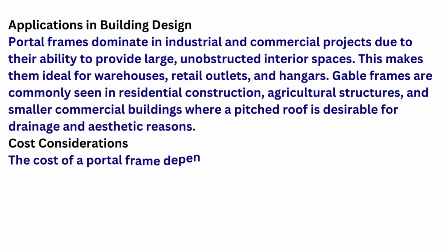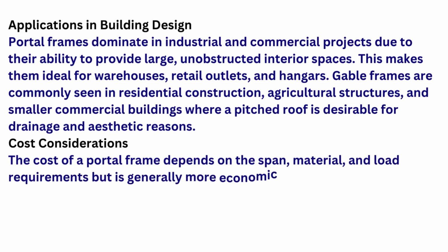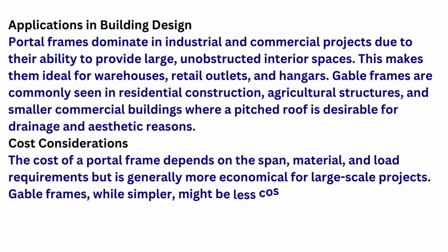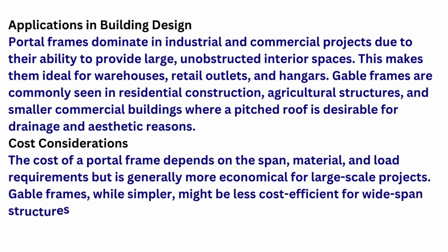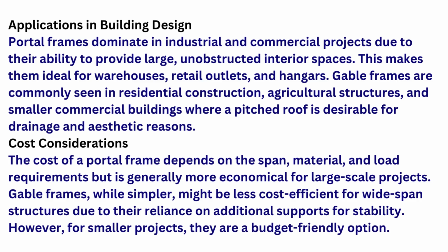Cost considerations. The cost of a portal frame depends on the span, material, and load requirements, but is generally more economical for large-scale projects. Gable frames, while simpler, might be less cost-efficient for wide-span structures due to their reliance on additional supports for stability. However, for smaller projects, they are a budget-friendly option.